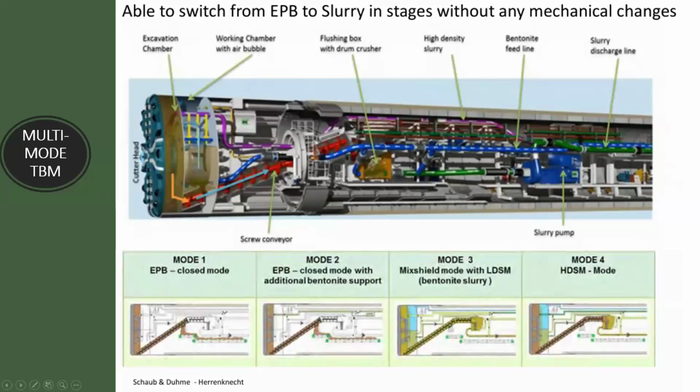So the TBM has a cutter head that is called the front shield, and the TBM has a tail end, and the segments are being fed from the tail end part. When it is being fed, there is a robotic arm inside the TBM which puts the segments in place as per a chronology. Now, initial drive means that the TBM is moving and it is installing the segments.